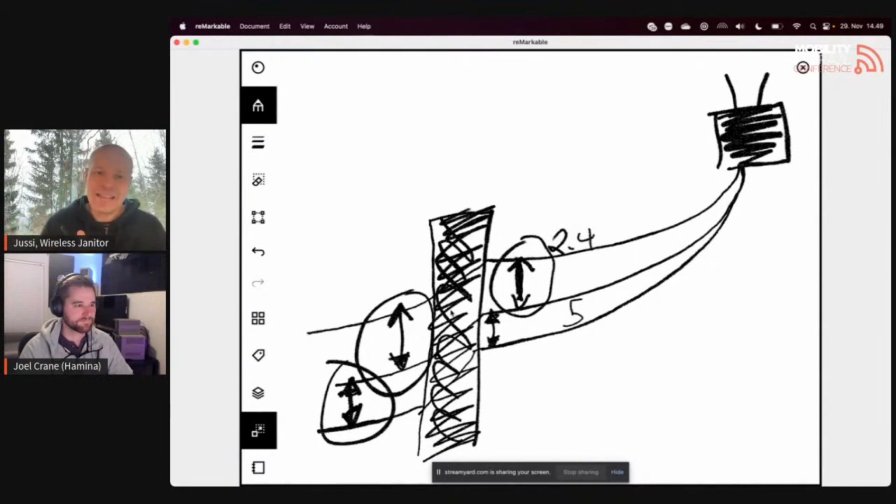Luckily, for the classic wall materials that are the most common, like drywall and stuff like that, 5 and 6 gigahertz behave quite similarly. But for some of the stronger and more exotic materials, like very thick glass and certainly concrete, the difference between 5 gigahertz penetration and 6 gigahertz penetration through those walls may play some role in the equation.